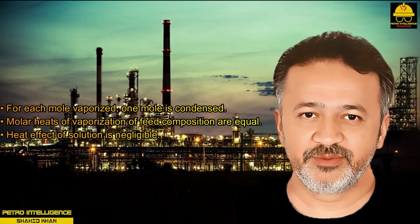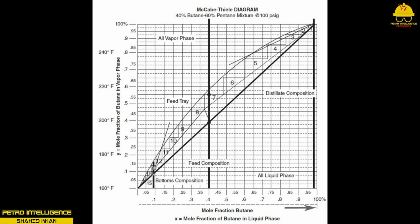A typical McCabe-Thiele diagram will show the mole fraction of the lighter component in liquid phase on the horizontal or x-axis, while the vertical y-axis will show the same mole fraction of the lighter component in vapor phase. Using this approach, a technician can correctly size a distillation column. This includes the number of theoretical trays in the stripping section, the feed tray, and the number of trays needed for the desired separation in the enriching or rectifying section.